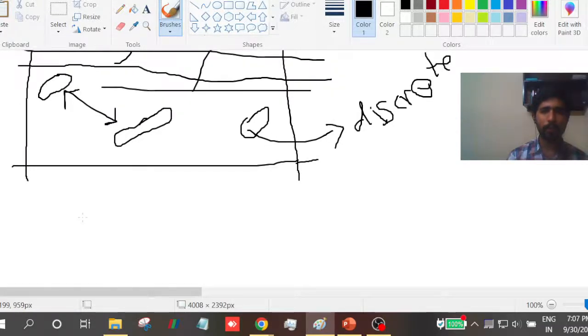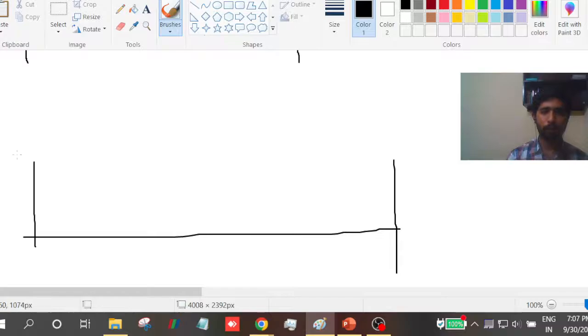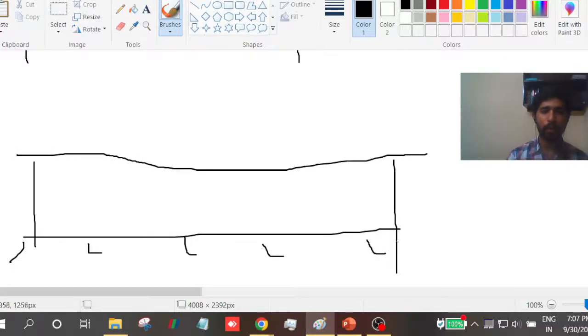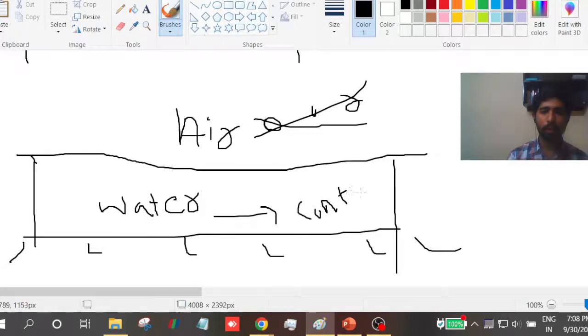Now similarly, if you consider just water flowing in a river, which is a free flow of water, free shear flow. So you have just a water bed at the bottom, say, and then this water phase is in contact with the air. So air is also continuous in nature, so that there is no breakage of air particles, and the water is also flowing in a continuous manner. So there are no bubbles which are formed. So this is just simple flow of water. Say you can say it is flowing at a very low velocity. So in this type of situation, this water is in a continuous phase, and the air is also in a continuous phase. So this is a second category of multi-phase flows.